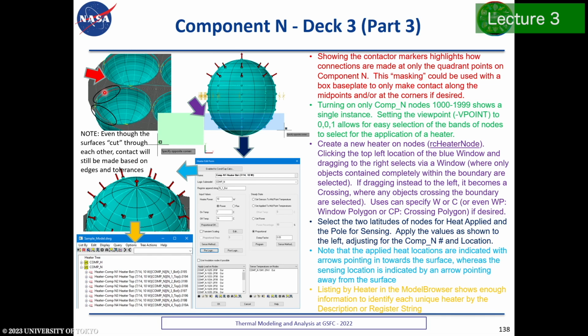And this is some places where applying the thickness can be a problem, because if it applies the thickness, then it expands the plane where it is, and now all of a sudden you might not make contact anymore because the thickness has applied, the plane has shifted the plane where it's trying to make contact, and now you're not on the right side anymore. So that's the reason I tend not to use the thickness.